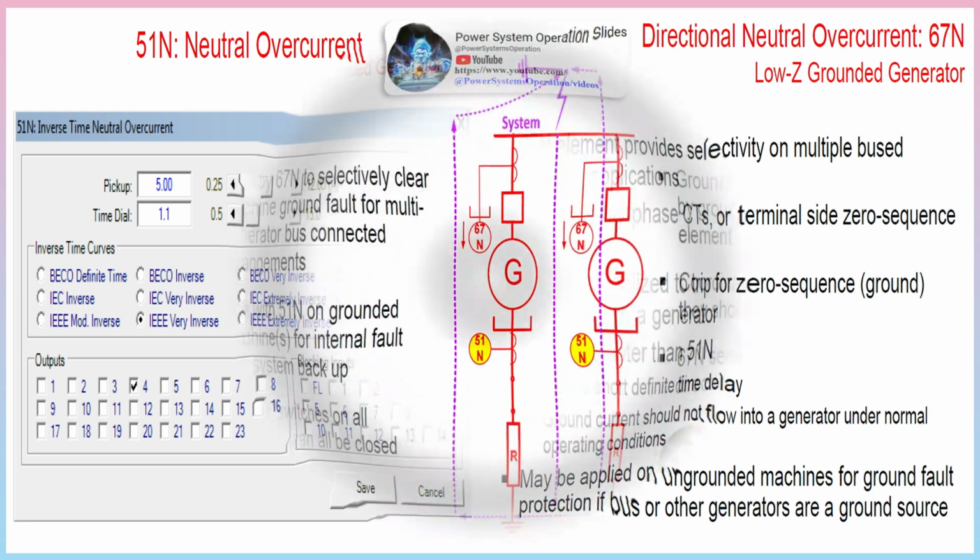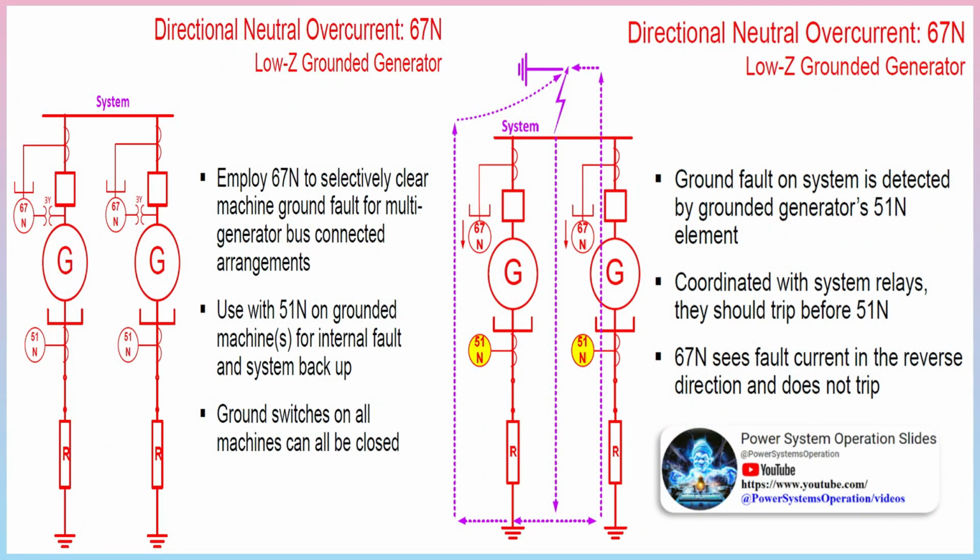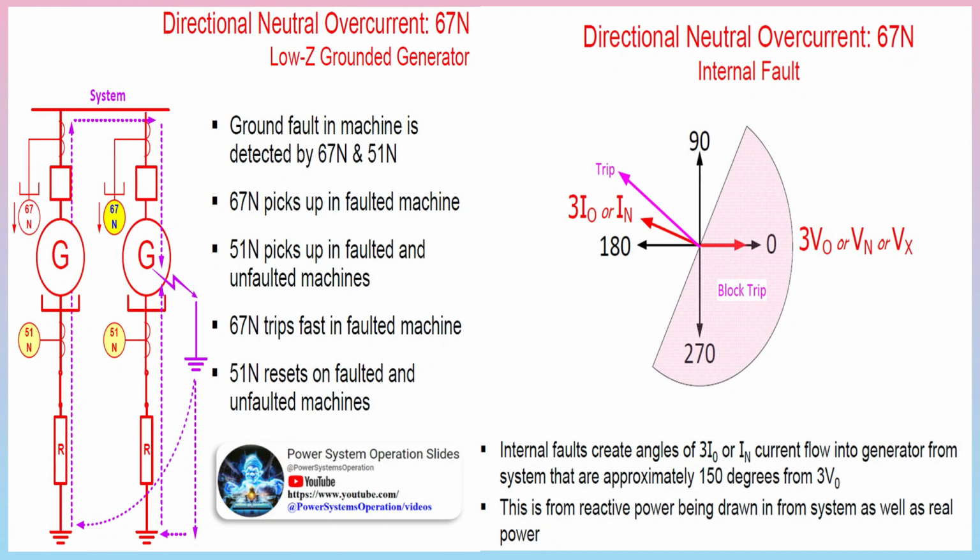Third harmonic develops in the stator due to imperfections in the winding and system connections, in an unpredictable amount requiring field observation at various operating conditions. It is also dependent on the pitch of the windings, which is a method to define the way stator windings are placed in the stator slots. Using third harmonic in generators, the capacitances C provide a path for the third harmonic stator current via the grounding resistor. This can be applied in protection schemes for enhanced ground fault protection coverage.